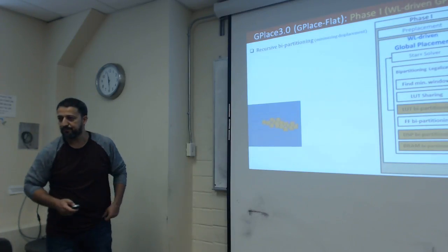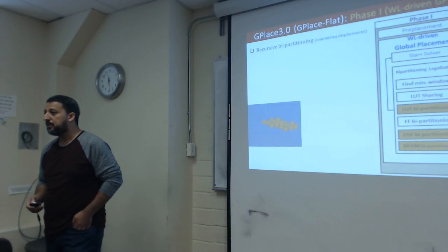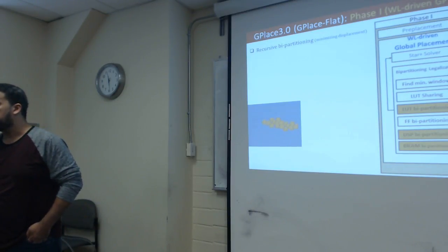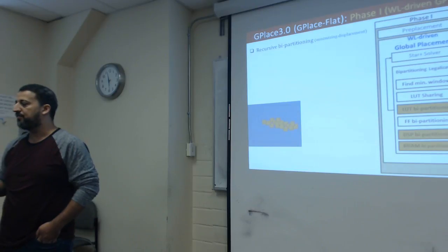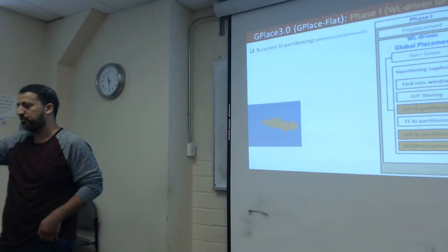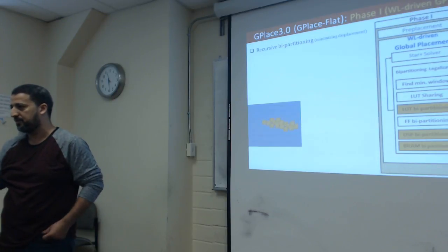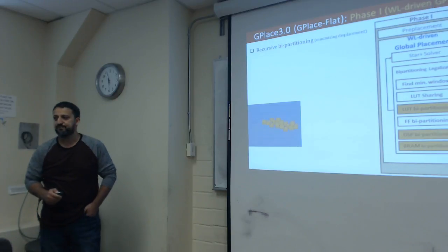Okay. So you do the LUT sharing after you've created your illegal placement, basically. So you choose two that are nearby, with maximum sharing, that are pairable, basically, legally. Yes. Before that, we have a hash table that has all the combinations for shareable, so we can do that very quickly. Sure, and all the combinations are legal, so you enforce legality constraints there. Yes.